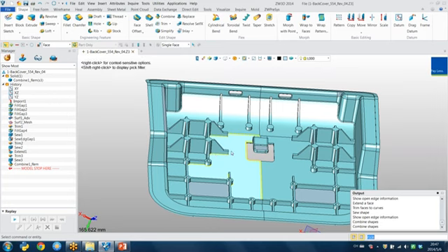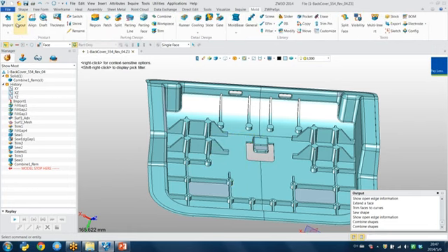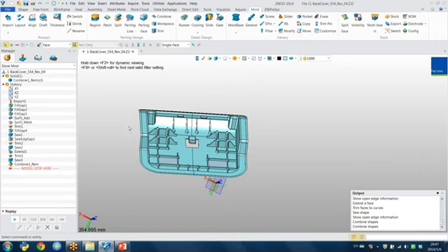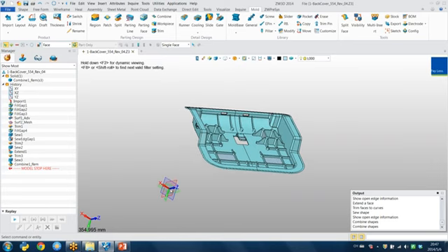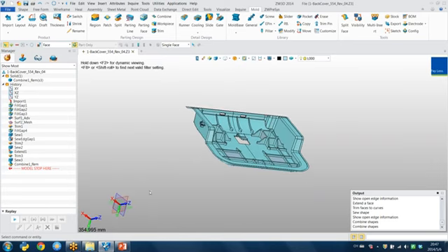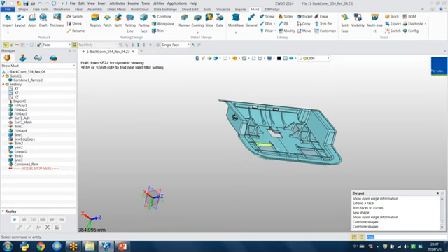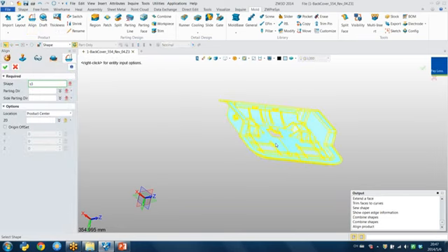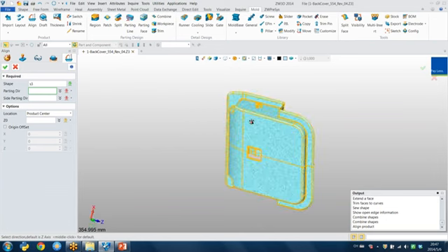So next, I would like to create a mold for this part. So you can find here, this is the whole process for mold design. So the first step is I need to align the part because this part is not at the origin point. Okay, so I want to put it at the origin point. If you use the basic functions, it's difficult to do that, but ZW3D supports align functions to do that very easily. So just select the shape and parting direction.